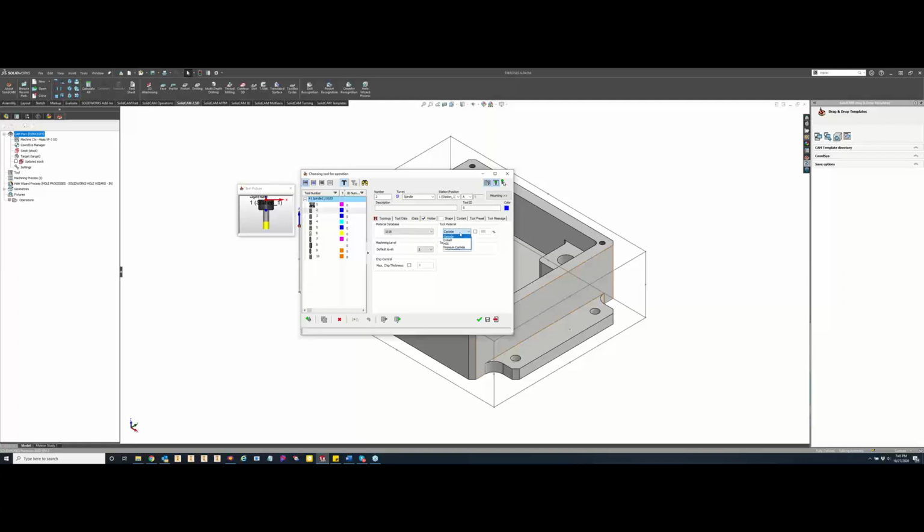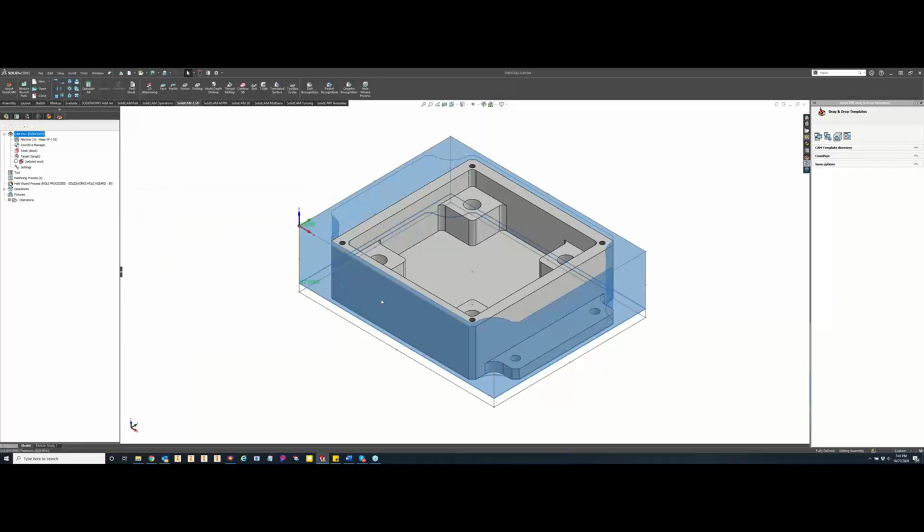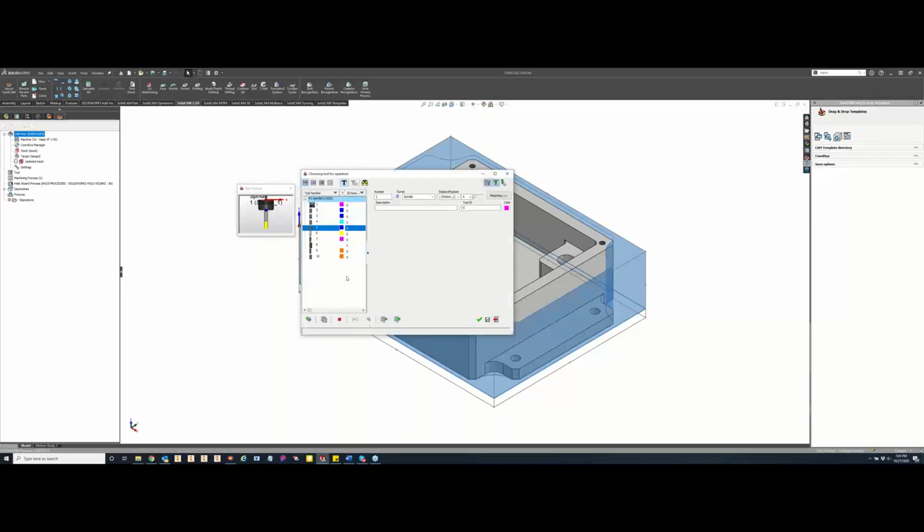We're cutting with a carbide. Usually I'm running premium carbide, or a coated carbide end mill, 45-degree helix. I can accept that. Now, how this would work normally is either A, I would come in here and get a measurement, or B, I would just play this through and see if I have any material left over. So now, since we know we still have material in the corners, I'm going to go ahead and grab my next tool, which is my 8mm.